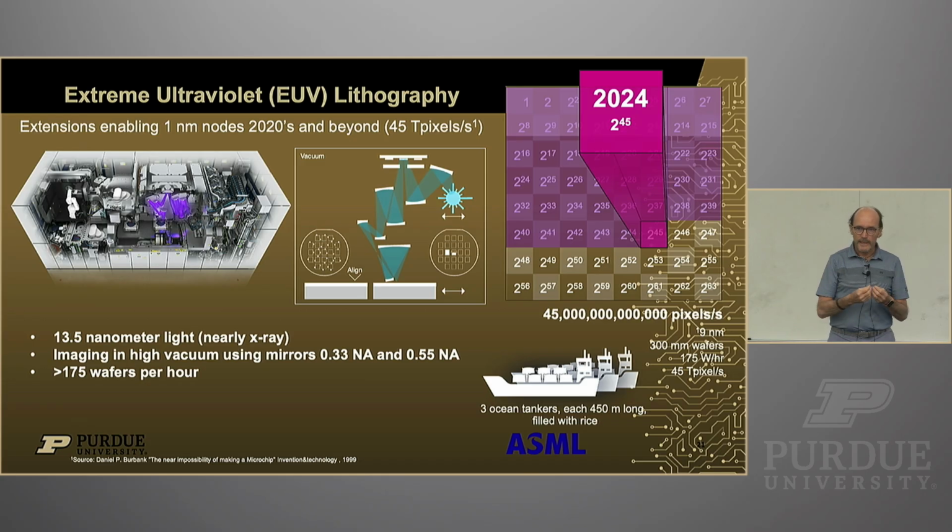But at 13.5 nanometers, every layer that I try to use as a mirror will only reflect 1% of the light. So what we then do is we say, let's have one layer of molybdenum, one layer of silicon. The first layer reflects some light. Next one, I have a silicon to molybdenum interface, I get 1%. Next one, I get 1%.